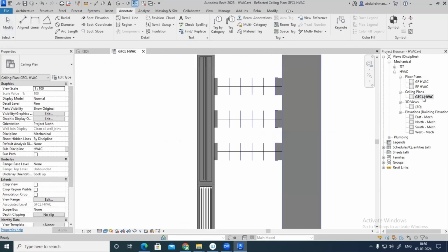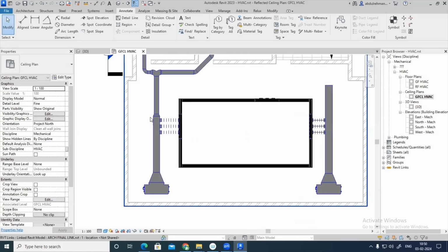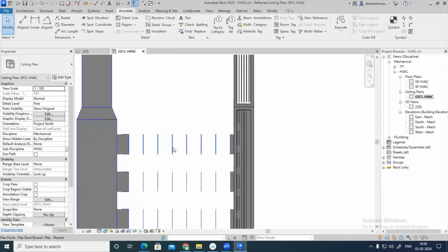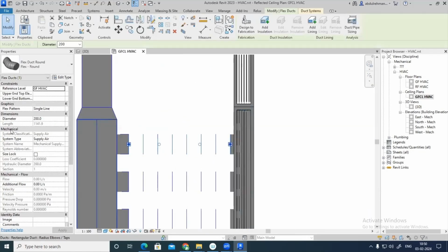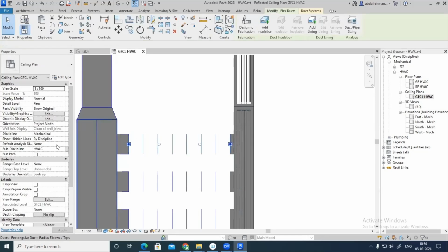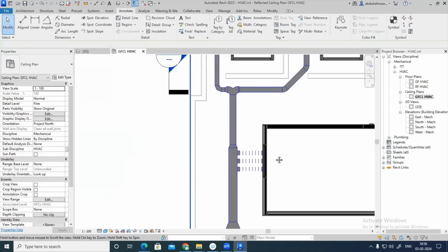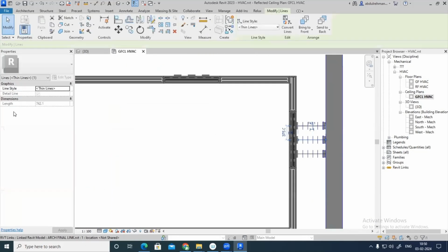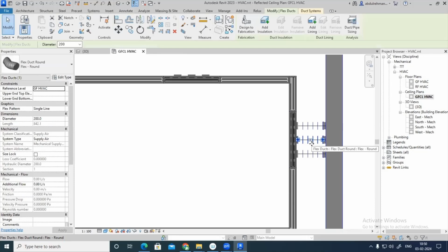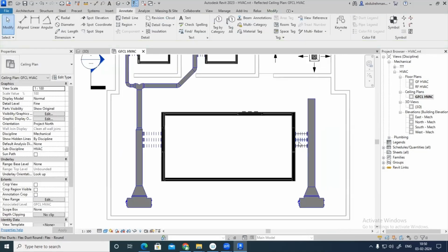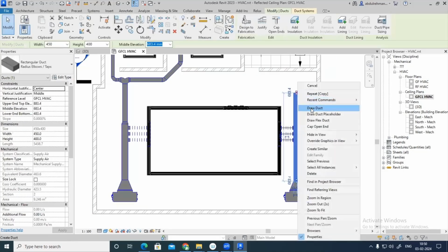Okay. You have to make sure that the flexible duct total length is less than 1.5 meter. Now you can see this length when you are clicking, you can see under the dimension category, the length is 1.141 meter only. That is fine. Here also it will come less than that. So it's not a big issue. 842. Fine. Now just opposite side I need it.